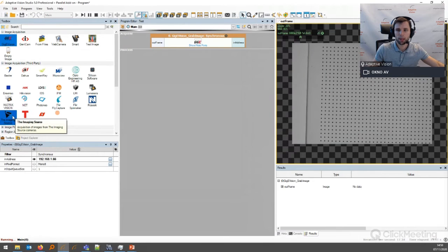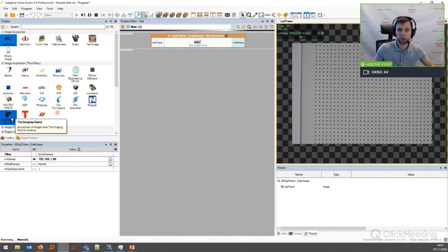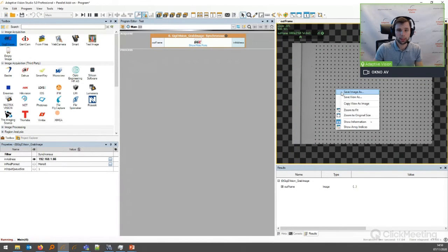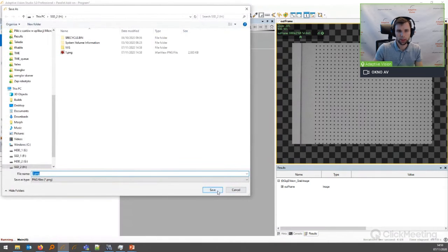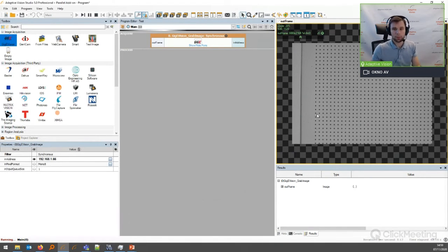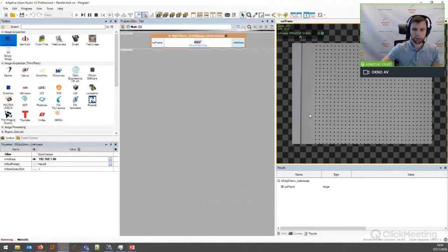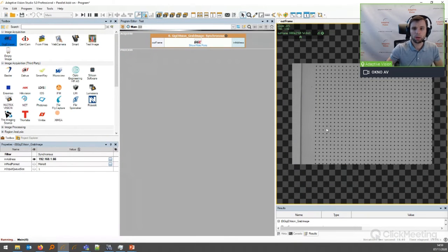As you can see, my calibration plate is covering almost the entire area, so it's enough to make 2 pictures. However, later we would like to also calculate the focal length of our camera, and for that case we need a calibration board presented at some angle to the camera.